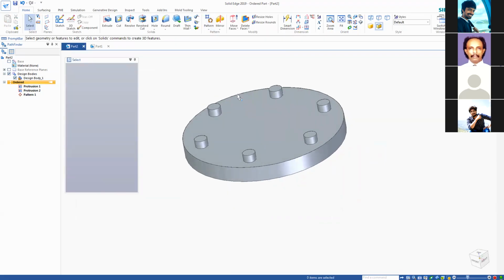And there are many variations of this one as well. Circular pattern may be very important for you because you want to create many gear wheels, right? You can create one gear tooth and then pattern around, because you cannot create them one by one. And when you create the gear wheels, of course, you can create one gear wheel and use that as a template and then generate all other gear wheels.